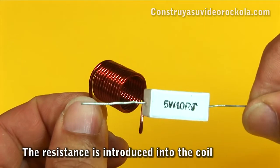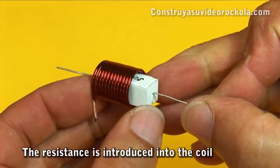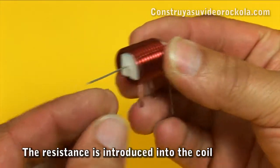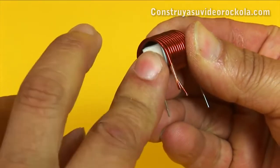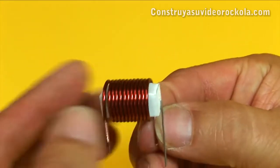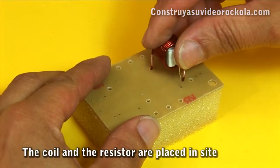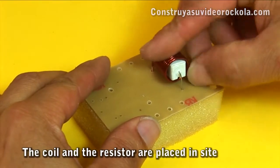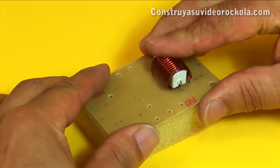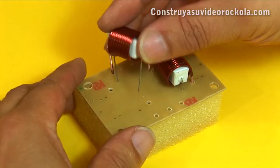The resistor of 10 ohms at 5 watts must enter perfectly inside of the coil. Then fold our terminals downward. We insert the set, formed by the coil and the resistance, in the PCB. We put the other set.